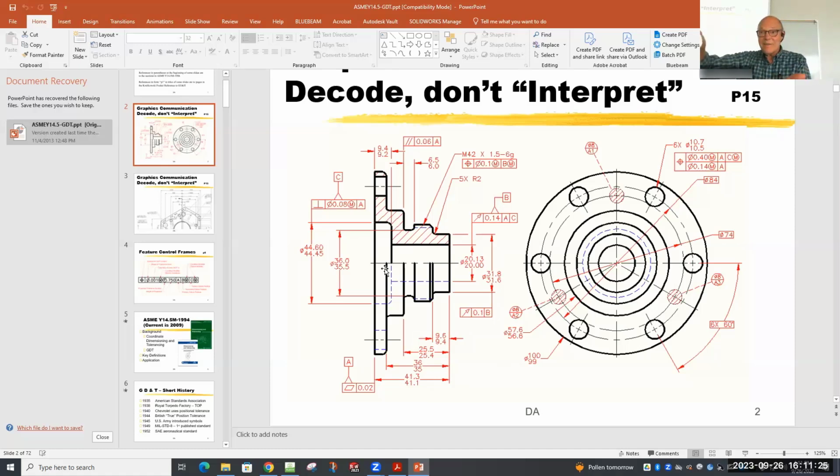So the flatness tolerance just means, listen, we're going to take that dial indicator and drag it all around that surface. We're going to lock it down. We're going to put this in something, it's a plate that goes on top of a flat piece of granite, if it's mechanical. I'll tell you what's happening now. Of course, you don't really use flat pieces of granite as much as we used to. Instead, you use a computer measuring machine or a coordinate measuring machine. This is an arm that has a little probe on it, and it's capable of measuring to within a tenth of a thousandth of an inch.